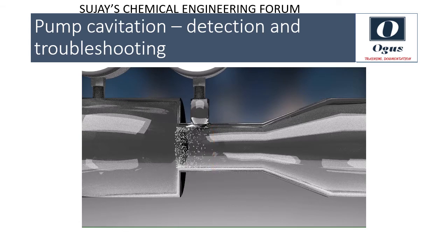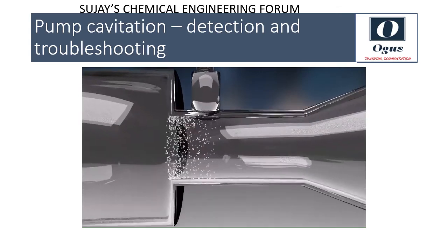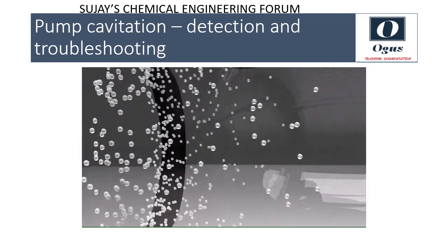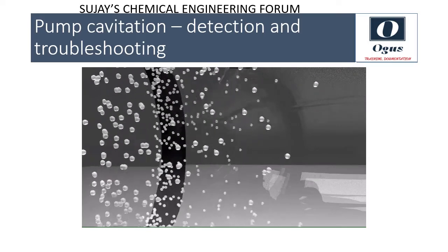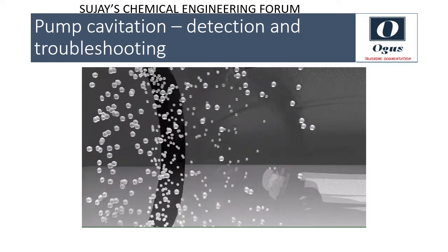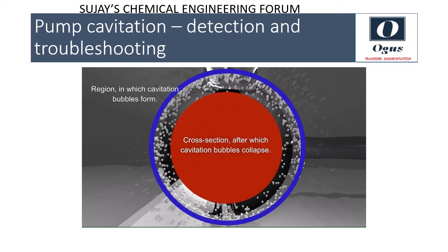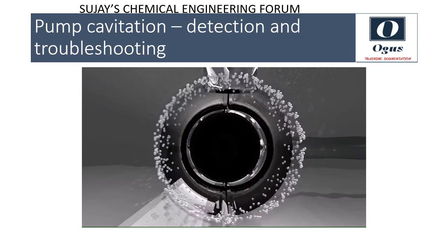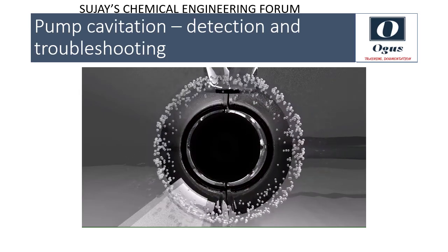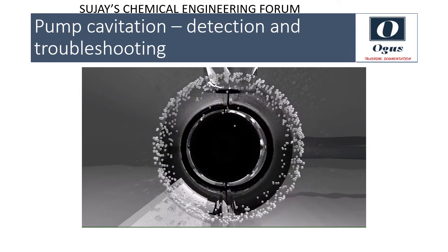Because water from the vapor bubble occupies 50,000 times less volume after having condensed to its liquid state, the collapse of each bubble is a spectacular event and emits pressure shocks. Pressure shocks from many collapses result in an audible noise very characteristic of cavitation. The sound used now in the video has been recorded in an experimental setup similar to the one in the animation.